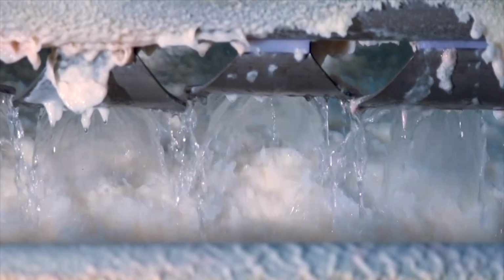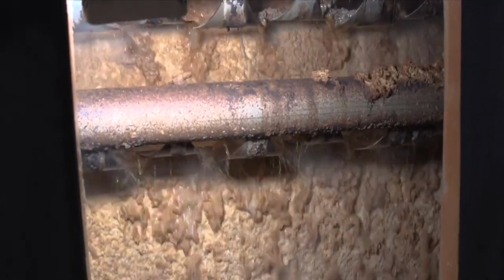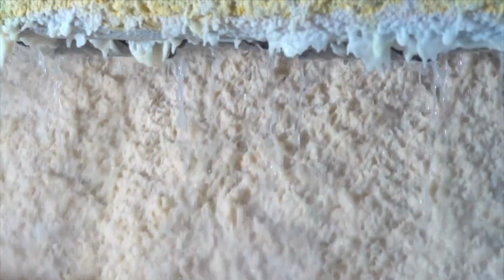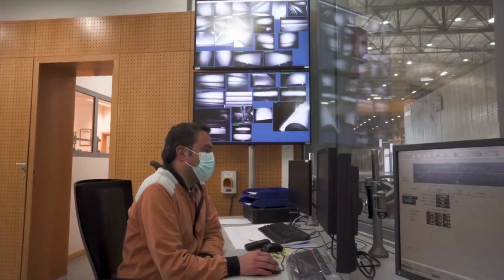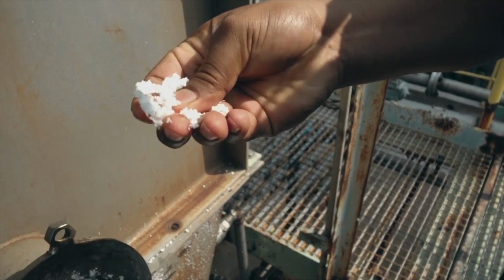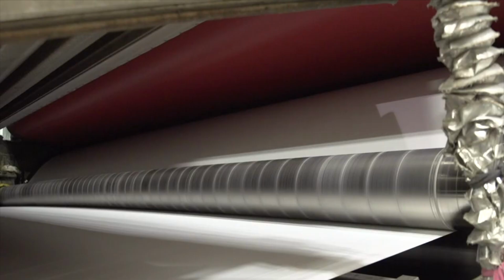Paper begins forming when the pulp fibers are mixed with over 99% water to make a very soupy liquid called paper stock or slurry. This fluid mixture gets poured onto a moving screen cloth belt that lets water drain out from the bottom. As more water drains through, the pulp fibers start crisscrossing to form a wet mat of fiber on top of the screen, similar to lots of tiny cellulose straws overlapping. The fibers bond during this wet paper web formation stage to create structure. Underneath the screen cloth are suction boxes that also help pull water out. Operators can adjust the slurry flow, screen speed, and other settings to influence how tight the fibers bond as the wet paper sheet is produced.